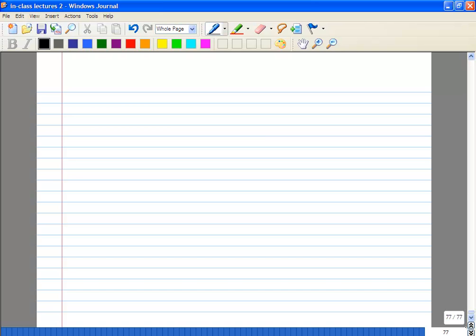So what do we know? We want to get a square law device. What device do we know that is a good square law operation? Your MOSFET in the long channel, that's very important. So long channel MOSFET. Let's consider it. So we want to give RF plus LO as the input.